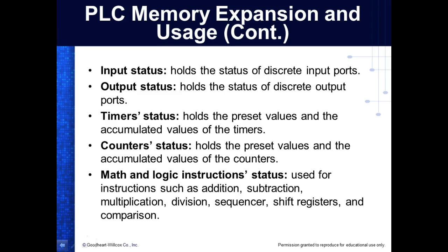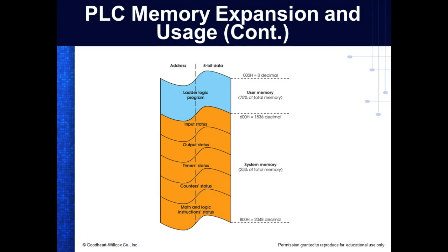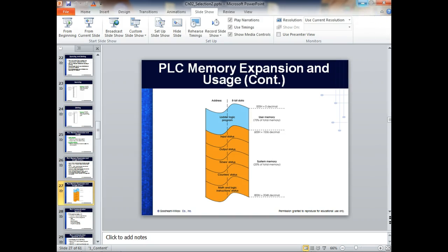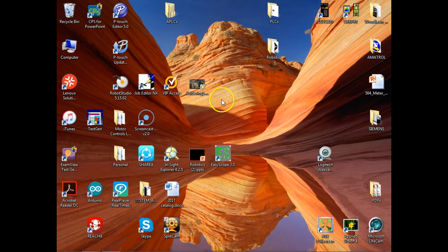Oh, in fact, it's right there. We have to have the communication cable that we use to connect to the PLC. This is an RS-485 or RS-232 port. Our computers don't support that port anymore. There's a lot of ports that they don't support anymore.